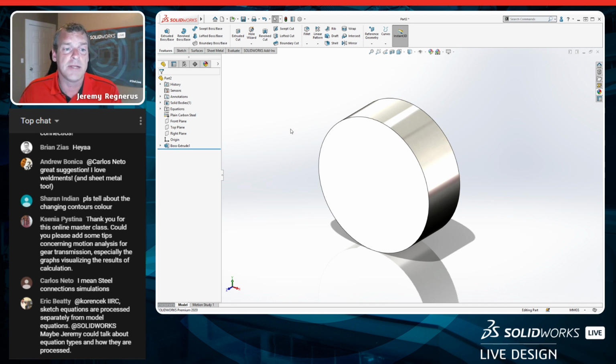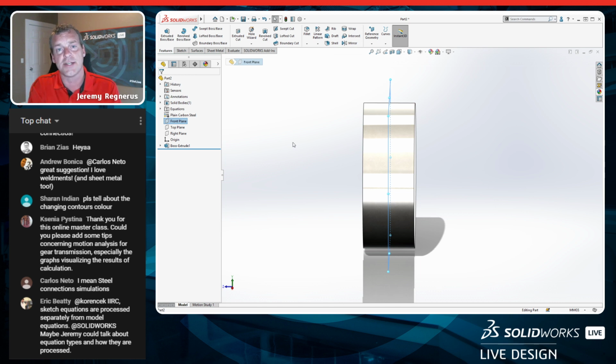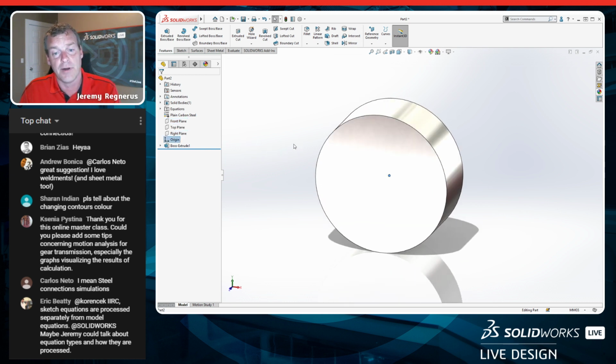By creating a midplane extrusion, I have set myself up for success by setting my front plane down the center line of my part. So now my origin is in the dead center of my part. That's an important piece of geometry that I'm going to be referencing as we go on throughout here.